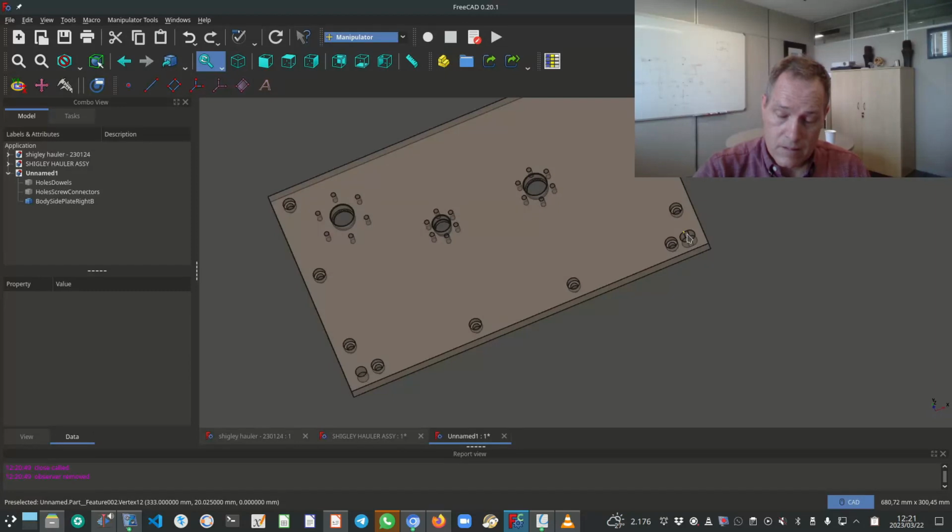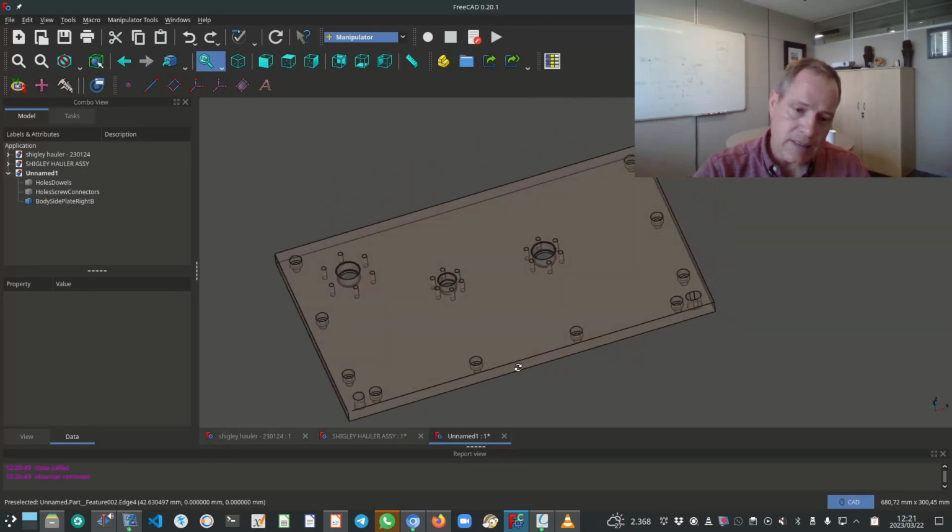Let's first talk about the dowel hole. The position of the dowel hole needs to be specified with the positional tolerance, and for that you need to specify at least 2 datums. So now what do we select as the datums?